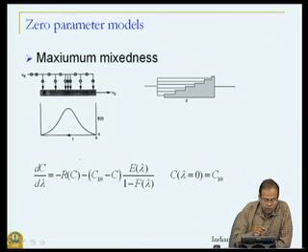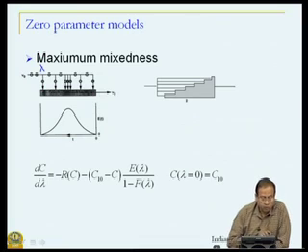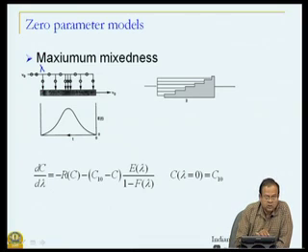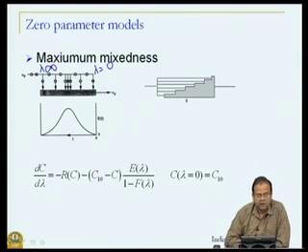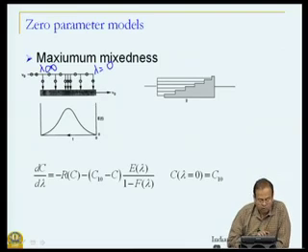If I call, for example, lambda the life expectancy of a fluid element in the reactor, the fluid element which enters at the inlet has the maximum life expectancy. So, I call it lambda alpha, whereas the fluid element which enters at the exit point of the reactor has a life expectancy of 0.